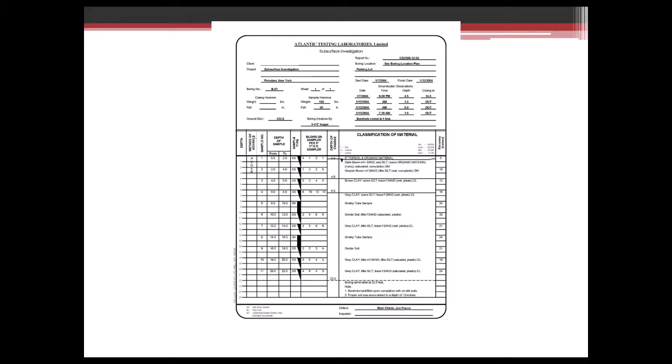Because of the conditions we found on the site, we were able to save a significant amount of building costs and not having to put deep foundations in for the building by moving the building on the site. That's why I say these borings were originally supposed to be in the building footprint, and then they moved into the parking lot because they swapped the building and the parking lot, and it was easier to control the settlement in a parking lot than it was underneath the building.